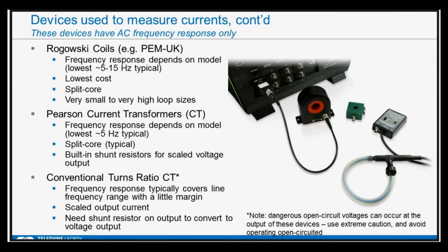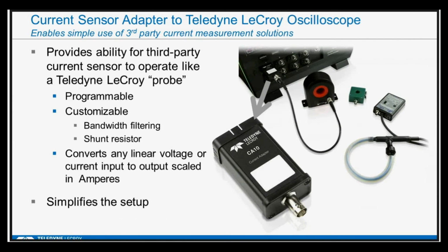Just be aware with a conventional turns ratio CT, you could have a dangerous open circuit voltage on the output. So you do always want to keep that terminated, not open circuited, when you're using it.